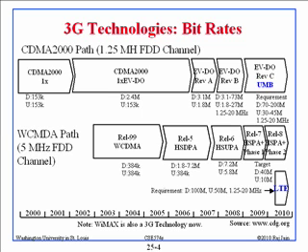Then CDMA 2000 with 1x EVDO. Actually, this should be called CDMA 1, I'm sorry, yeah, CDMA 1, because 1x is CDMA 1. So this is 2G technology. In 2G we didn't have really high-speed data. All we had was a voice channel on which you put data, something like that. So that's why it is so low, kilobits. This went to megabits, 2.4 megabits. This is the first level of 3G. Went to 3.1 megabits and stayed around that range.